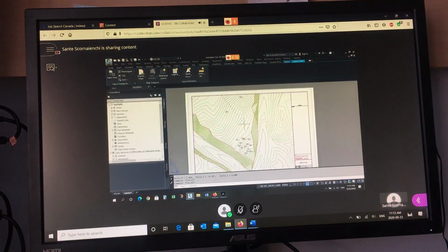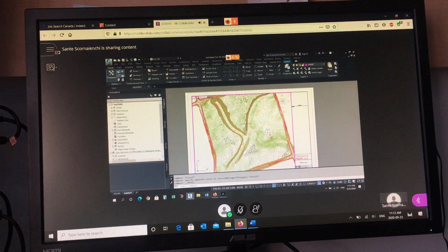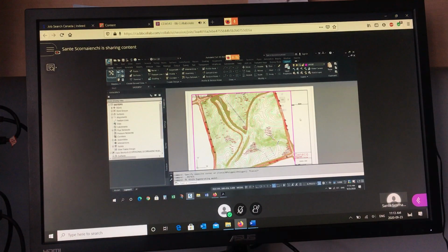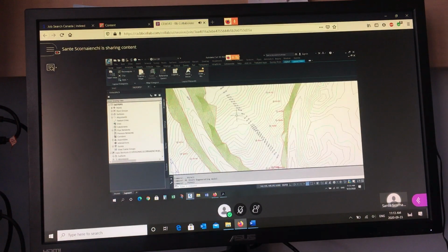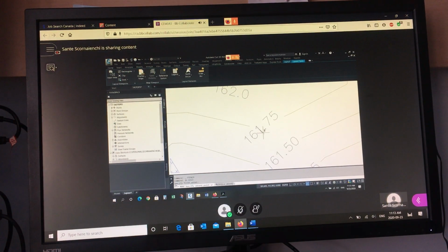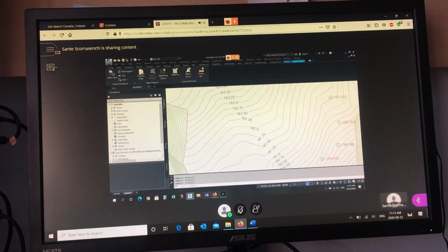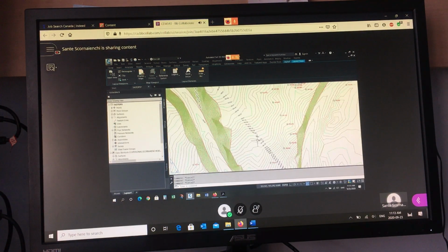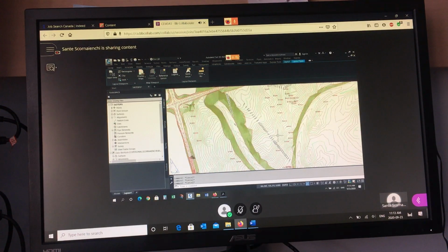Right? And if you, again, disturb that, it just got smaller. If I regen, the numbers will get bigger. And what size? Back in paper space, the same size it's always been. Again, the height of this is always going to be 1.5. So if you make it twice as big, the text gets half size. If you make it a quarter of the size, it gets 4 times bigger. It's always counteracting the zoom factor. The smaller the zoom, the bigger the text. And then the opposite's true. Okay, so it's always counteracting that.